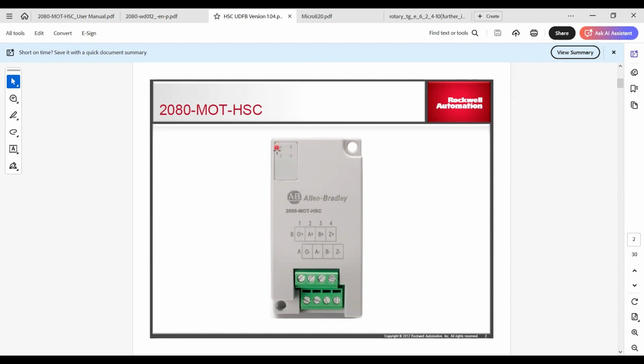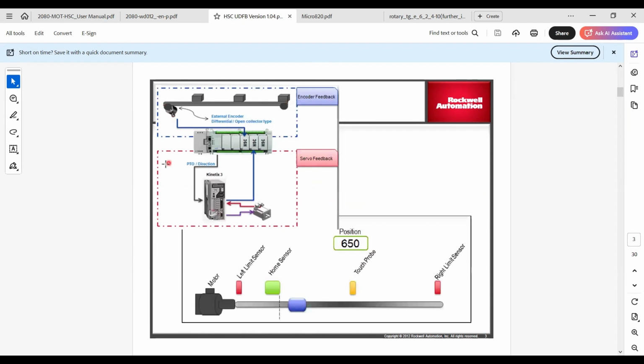You can actually see A is blinking. So they can be used just for visualization, to see whether you are receiving a signal at this high-speed counter and it is working properly. And there are several applications of this high-speed counter, as mentioned in these application examples. You can use it for linear encoders that can be directly coupled here, or sometimes in servo drives, where it is driving a servo motor so that it is feedback driven. Sometimes there could be a feedback output that can also be sent to your PLC just for reference.